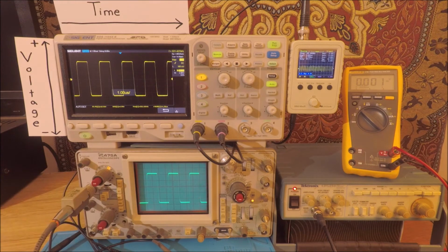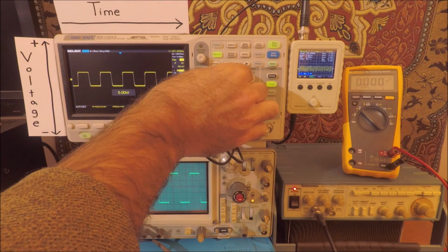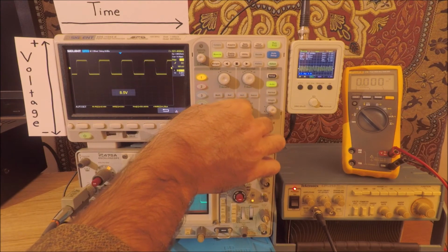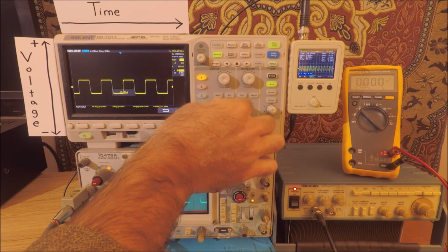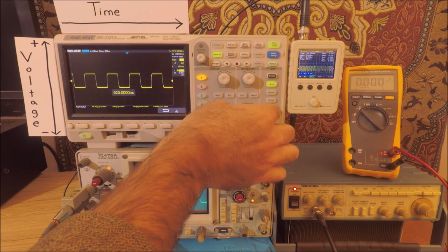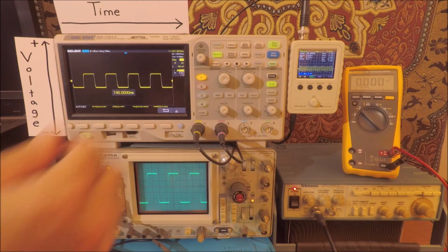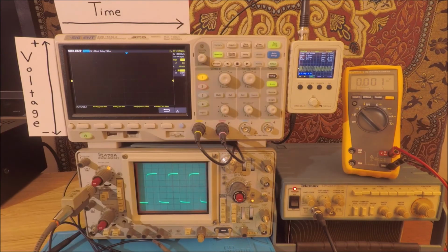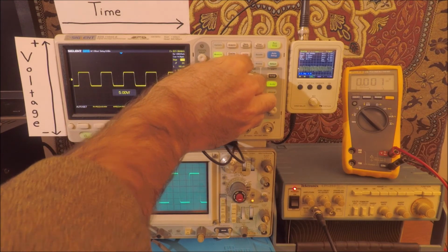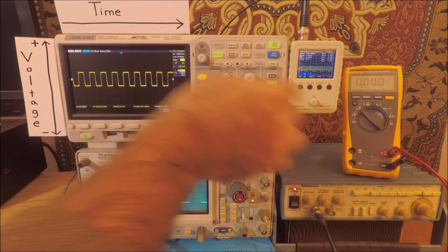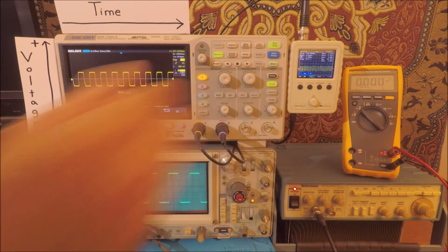There's some secondary controls that some people like to use, especially if you're connecting multiple channels, to offset the position of each channel. So you can change the vertical position, and as well, you can change the horizontal position of the waveform. So a lot of times, the easiest thing to do if you're coming up to an oscilloscope that someone else was just using and things are a little out of whack is to hit that auto scale button, get things into the ballpark that you'd like, and then go and fine tune the primary controls, to get what you would really like to see between the vertical, the horizontal, and of course the trigger control right here.